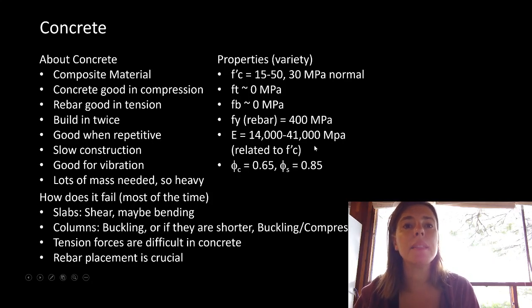E is related to f'c, or the strength of concrete in compression. You don't need to worry about the equation for that, but it ranges between 14,000 and 41,000 MPa. Again, it's a fraction of what steel is, but we can calculate it and make use of it. Concrete,